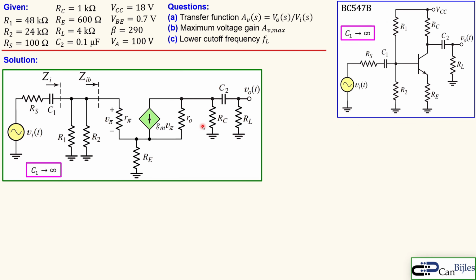Okay. Now getting back to this frequency analysis, and we now use the AC analysis to determine the cutoff frequency again. So we need the r_pi, and we can do that because we have the DC base current just determined in our DC analysis. This is the thermal voltage, 26 millivolts approximately at room temperature. We know this DC base current, so that will result in 935 ohms.